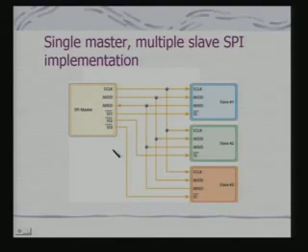And here therefore, you have got distinct slaves related to the master. So, if I have a problem of interfacing a device, and I know this device will always be a slave device and it is not likely to become master, okay, to take up the basic job of initiating a transfer of data on the bus, then I would select SPI as a protocol mechanism, because it enables me faster transfer. Okay.